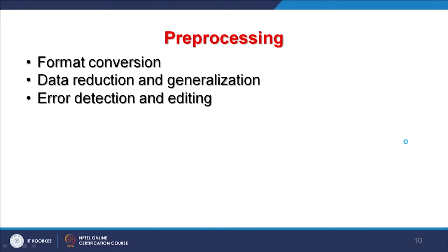After each and every step, check for errors, that is the error detection, and if found, do the editing, correct it and then move for next. Like if I have digitized something, now my topology has not been constructed properly, so I should check for errors, construct the topology properly and then go for the next.